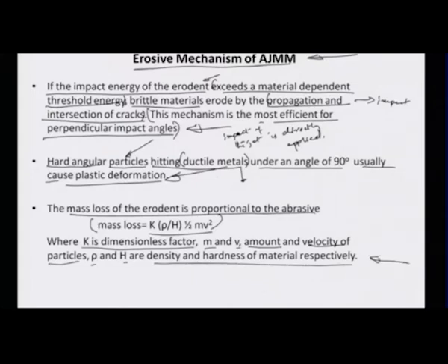So in micromachining, particularly when using a mask and when hitting ductile metals comes into the picture, there is a virtual loss of the abrasive, calculated by this method, in terms of damage or deformation to the total quantity of grains which emanates from the nozzle.